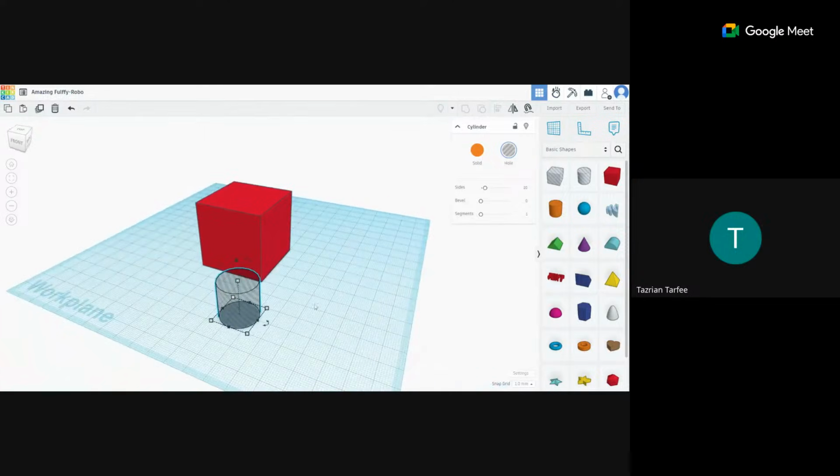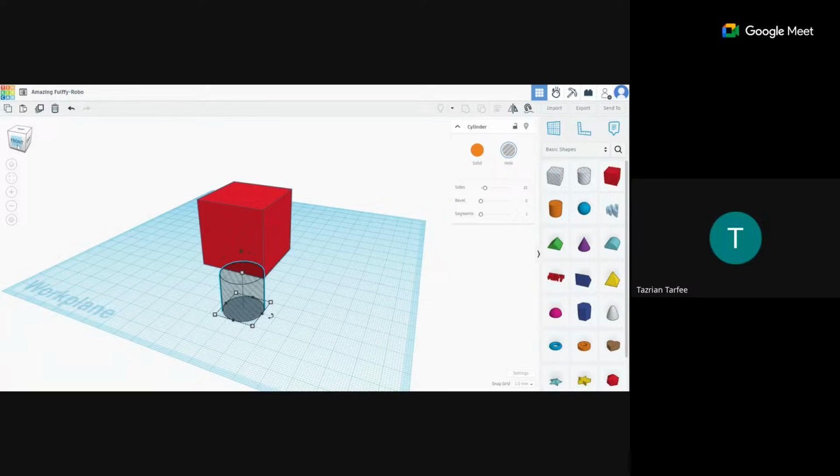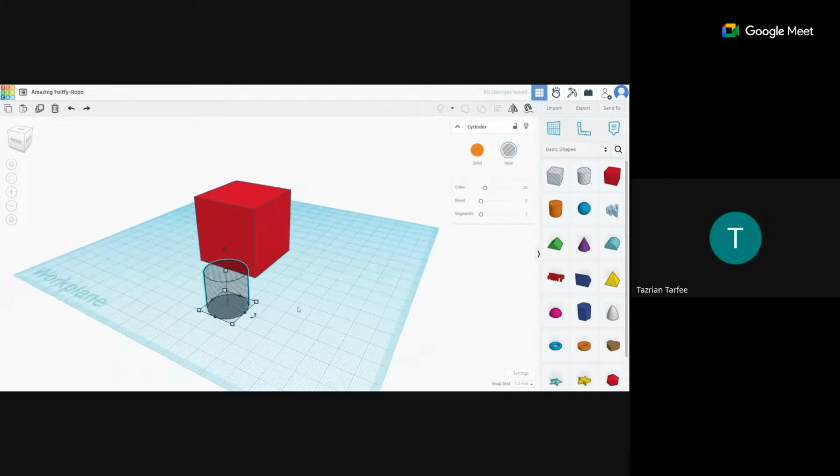But you are going to need to rotate your screen a little bit, just enough so you can see the curved arrows. So it's going to be 3 curved arrows. We're going to use the one that's on the side, not the one at the back or the bottom, the one on the side. And we're going to rotate it 90 degrees. So again, I can show that again. Select the shape, rotate your screen so you can see that curved arrow, and 90 degrees.